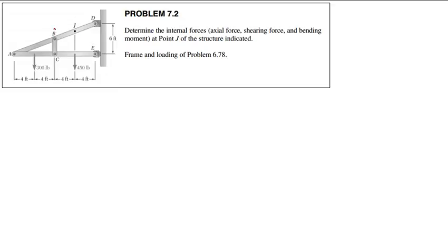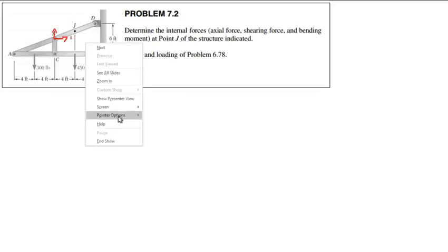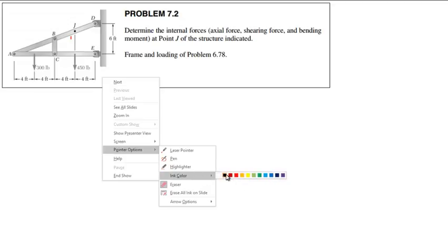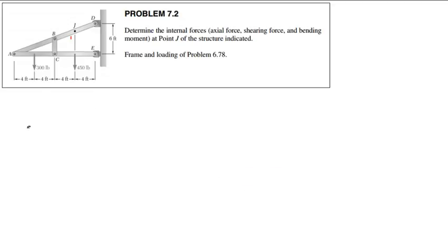Okay. So this will be a bit of a review on reactions as well. Actually, let me draw this as an exploded free body diagram. I think that'll be a little bit clearer than trying to do this on there. So we're going to have member ABD. I'm going to be looking for the reactions and the joint forces on member ABD: A, B, and D.